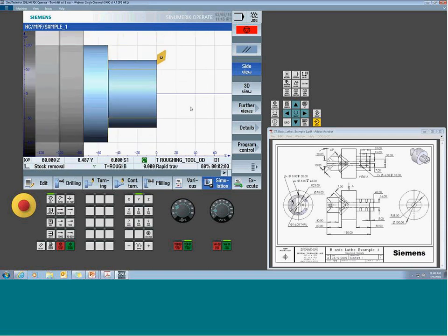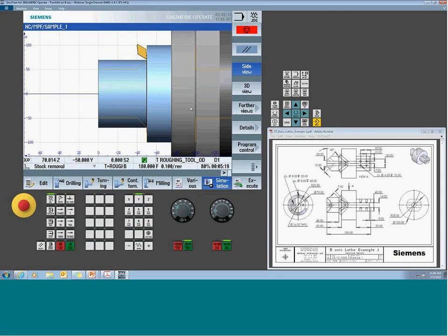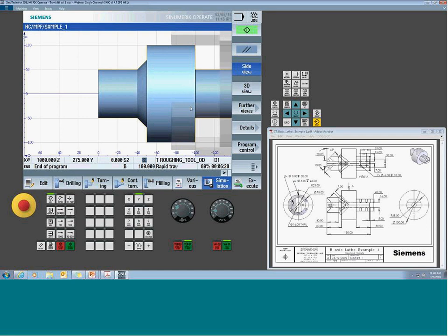So turn, I see insert screw, so where I'm sitting as far as the B0 and the spindle orientation, there's our transfer. And you can't see the insert screw anymore. And the counter spindle is actually running in reverse. The system will do that for you, by using the mirrored work offset and allowing us to track the beta and the gamma. If you want to do all this with B-axis positions and positioning the spindle, you can start to see how complicated this becomes. What direction do I have to run the spindle in? Am I inverted? Am I not? It's just tracking all that for us.